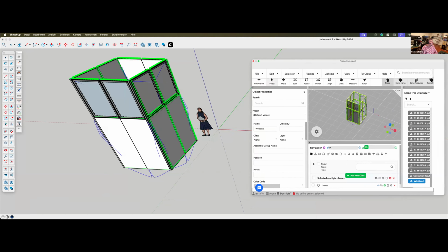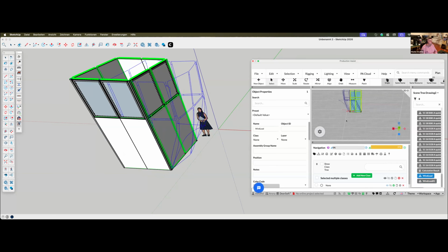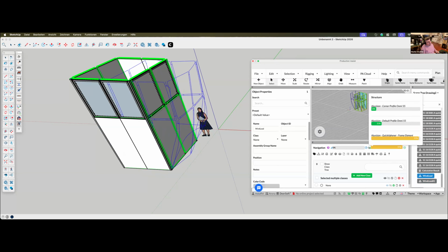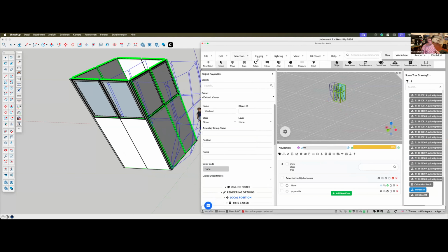So then as the next thing, you do it again for the other sides. You only need to do this for the 2 sides of it, so that you have both of them covered. And if you now look at this, you see that it moves to the side. So now you also have a quite larger wind load approach. You see, now it jumps to 97% use case, because now there's a way more vertical load. So remember before it was only like 2.5%.